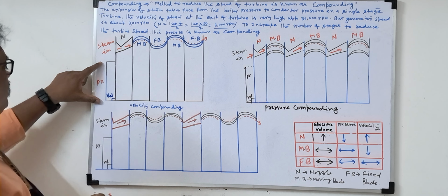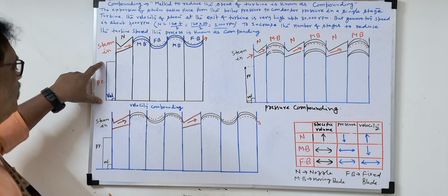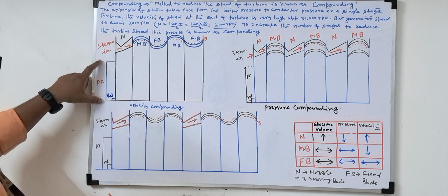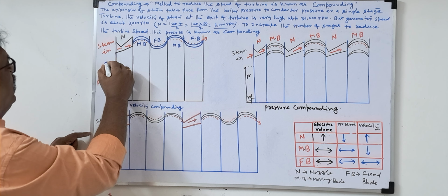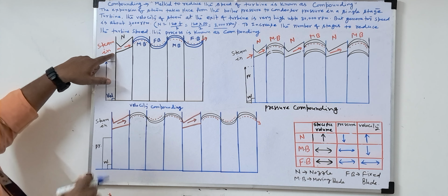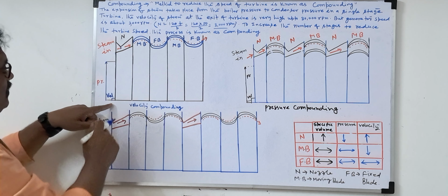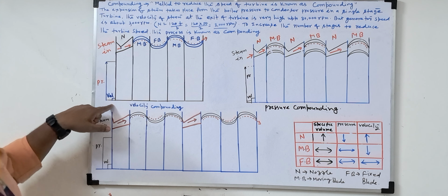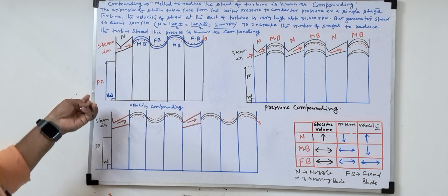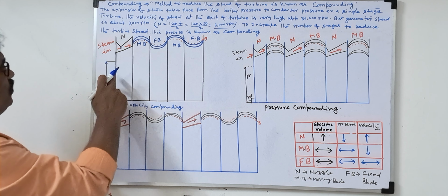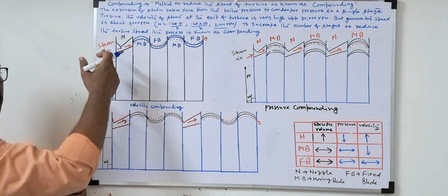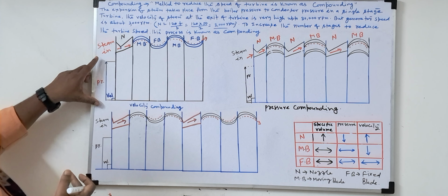Initially, steam generated from the boiler is very high energy steam, at high pressure and high temperature. So the steam pressure will be very high initially. But the initial velocity, when steam enters the nozzle, is approximately negligible, some very small velocity, 2, 3 or 4 meters per second. At the beginning of the nozzle the velocity is almost constant, but the pressure will be very high.